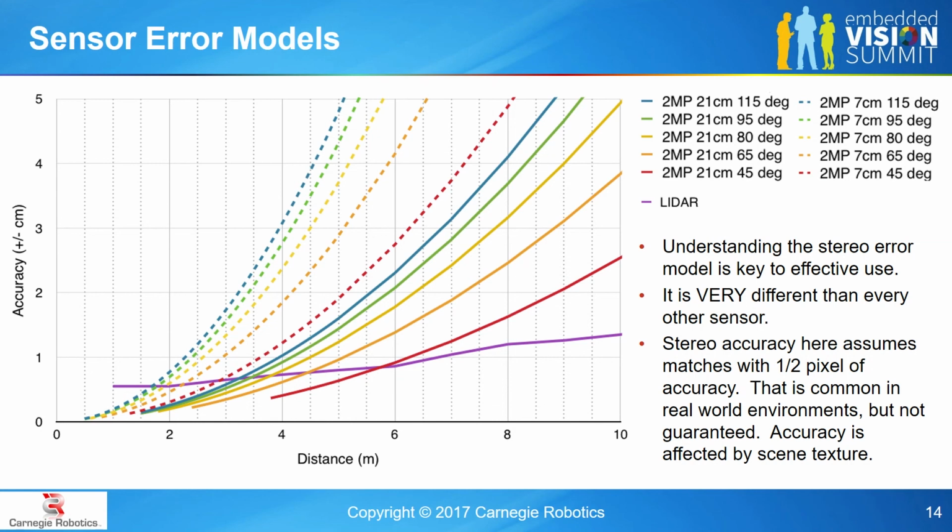But also, because of how these systems work, there's no maximum range generally for a stereo camera, unlike a time-of-flight camera. So they are very useful in mapping and safety tasks. You just have to know that they are not going to judge the wall of this room on the other side of this hall from me as well as the distance to the podium. There's this very different accuracy measure between near and far.